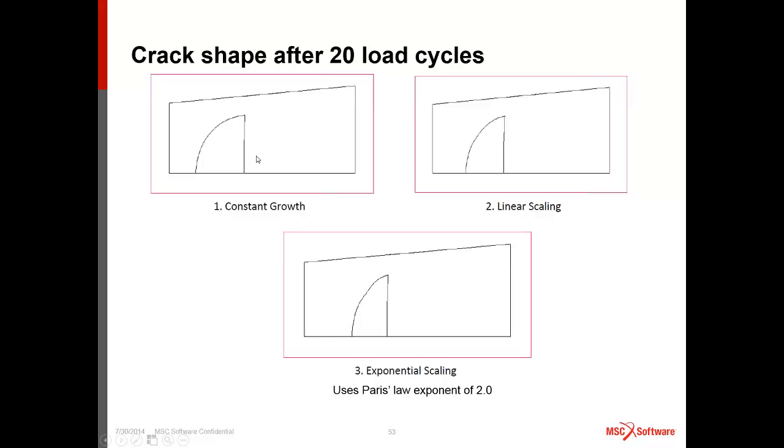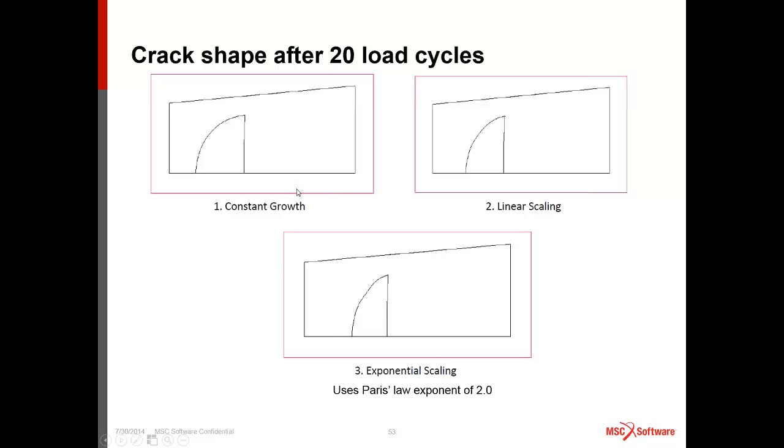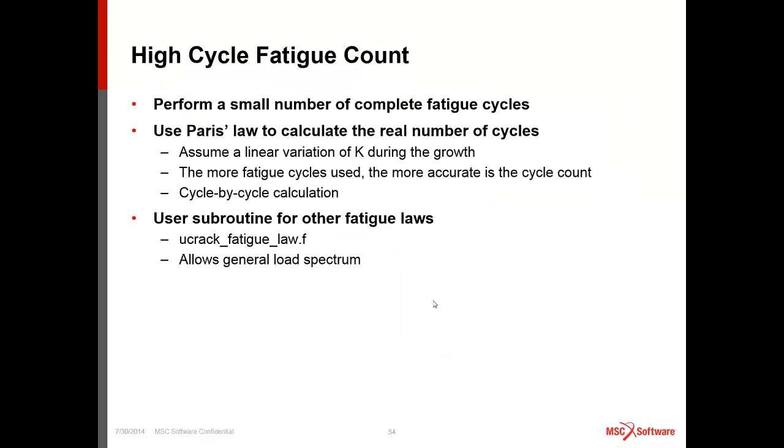And what effectively would occur before, so let me go back to the previous one, what we're really interested in is how the crack grows in this direction and also how the crack grows in that direction. In other words, how does the crack face change? And what one can see is if one did the default, we got a crack face that looks like this. This is much smoother than it was in the past. In the past, you would have had all sorts of oscillations here, so we locally smooth things. And then we can scale things to determine what sort of procedure for the crack evolution.